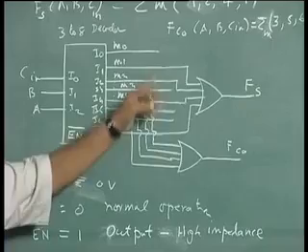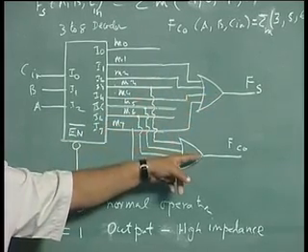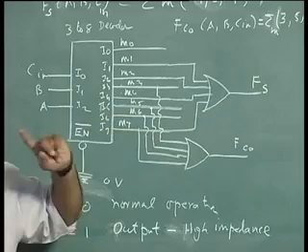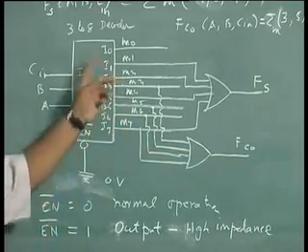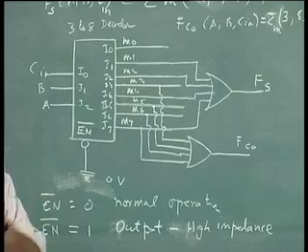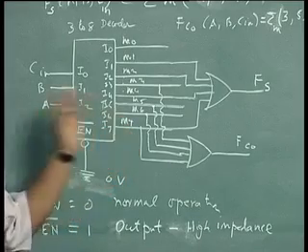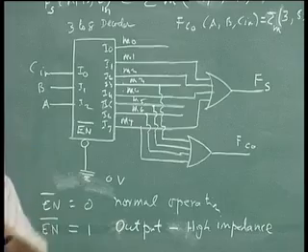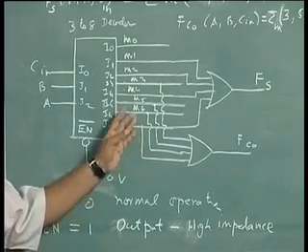Because I have connected these 4 into an OR gate to get sum, and connected these into another OR gate to get carry, assuming these were active high. But now I learned from the data sheet that these outputs are not active high, they are active low. So, now with active low outputs, how do we change this design?